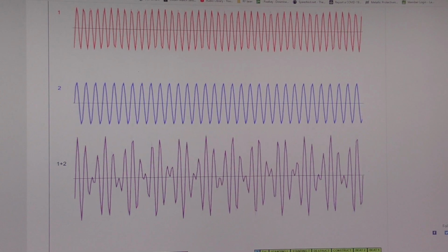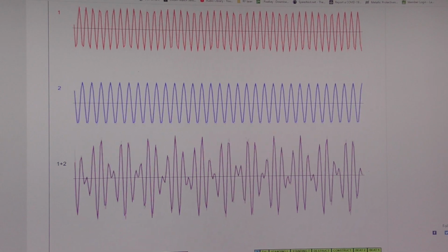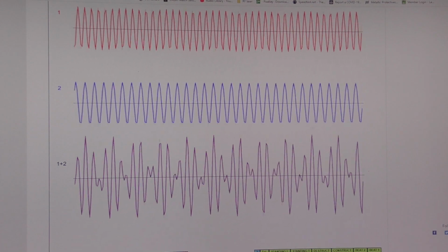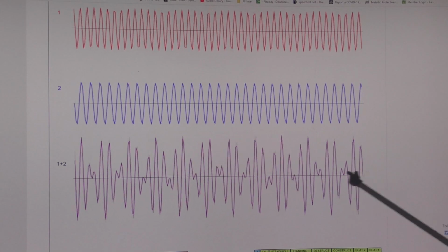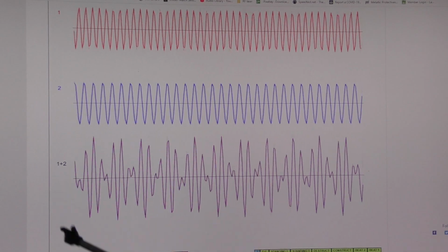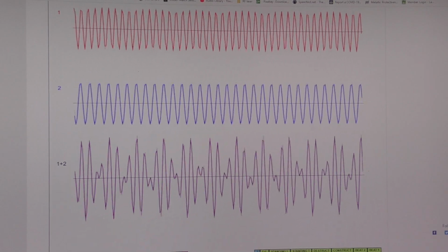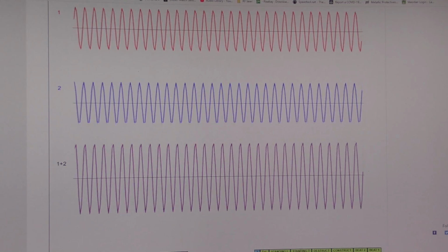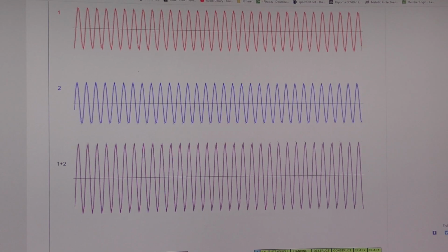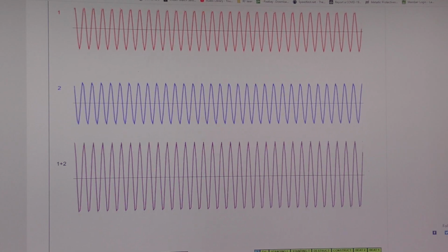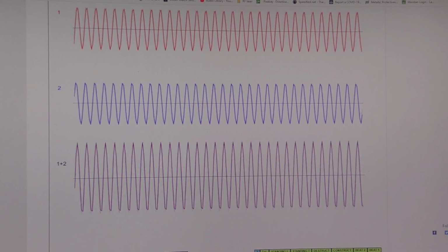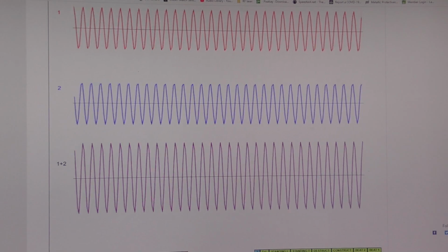So last time when I did my more successful picture, the second picture that I created, effectively what I've done is this. I changed the frequency to 9.7 kilohertz instead of 10. And so I've got this very rapidly repeating but small pattern, which you don't really notice. But you've seen in today's image, when I get them to match perfectly, how all of a sudden it becomes super crisp, lighter, and we get more definition in the picture because we're getting perfect information in the picture, not distorted information in the picture.